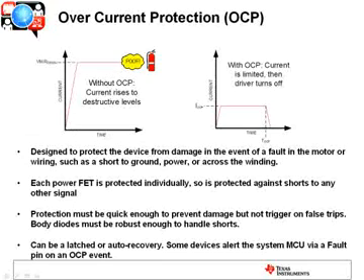Okay, so probably the most important protection is overcurrent protection. You've got pretty high supply voltages. These motors inherently have low winding resistance, and you're always worried about the potential for shorts, some type of short to ground, to power, or across the windings. So you want your motor driver to be protected. The trick there is to have protection circuitry that can trigger fast enough to prevent any type of damage, but also be intelligent enough to not trip on false trips.